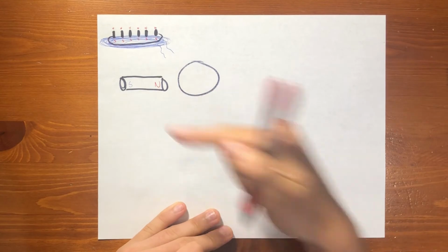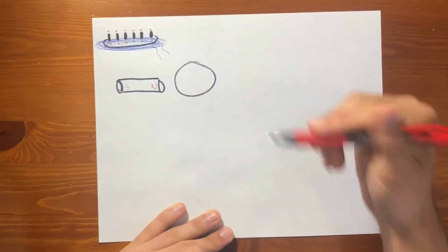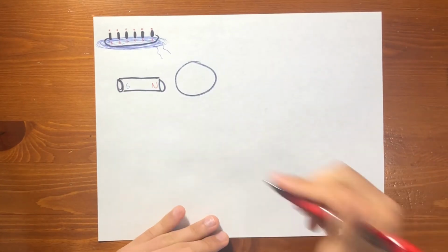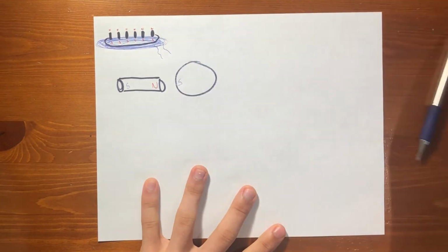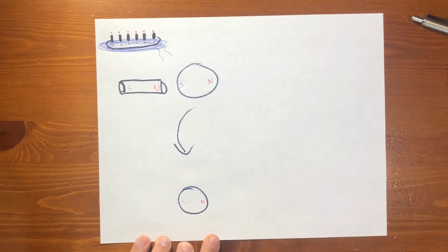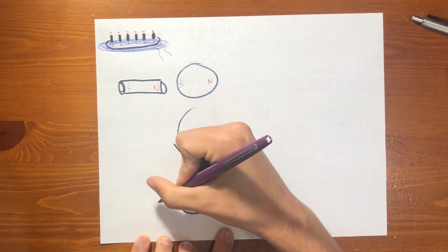So here's the pole piece, it's a magnet, and here's the string. Imagine the string as coming up towards you. Both of these are made of ferromagnetic materials, so the string consequently will be magnetized, something like this. Because the string is magnetized, it will have its own magnetic field lines, and it might look something like this.